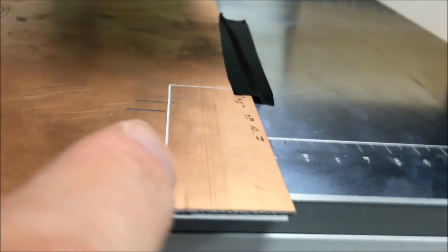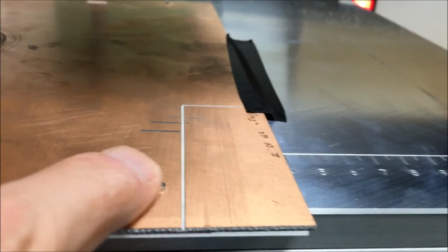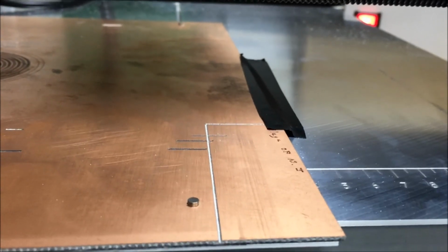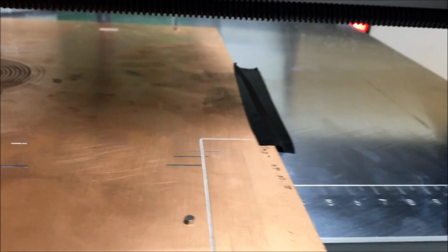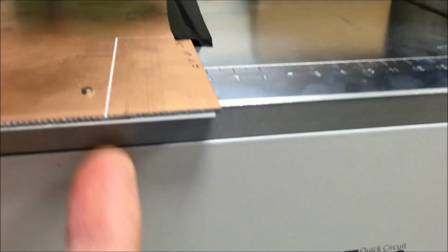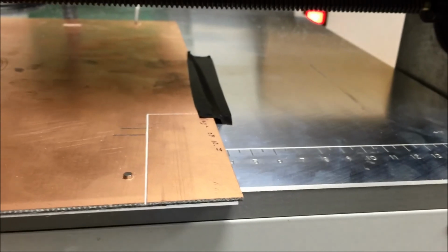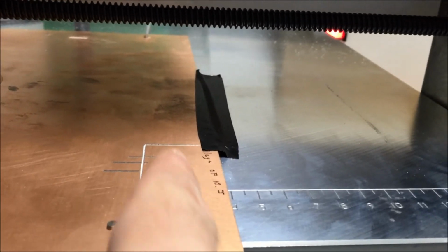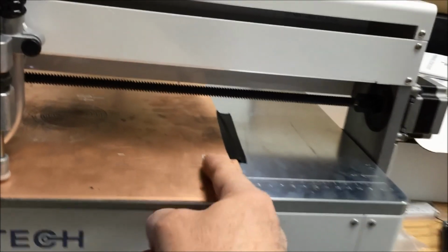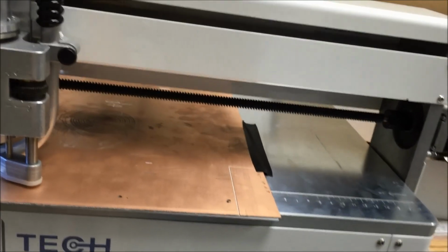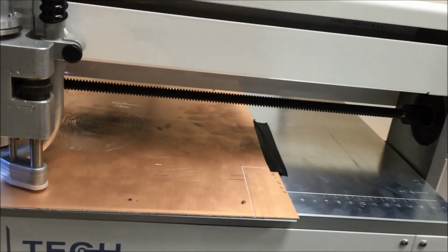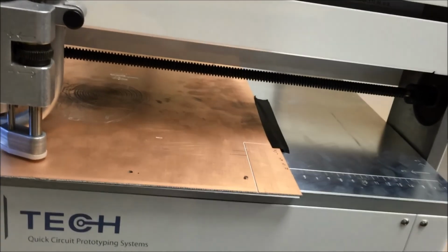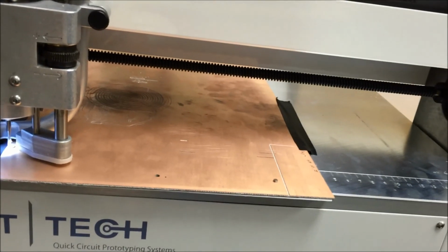So just to point out again, there's a pin that goes through here. There's a hole that has to be drilled through the board. It's 1/8". Okay, and you just press fit the pin through the hole, and it goes into a hole in the actual platter of the machine. And then there's another slot that runs all the way up and down the machine in this axis, a groove, and then the other pin just rides in the slot, and then the 2 pins together keep the board immobile and give you a reference that if you were to flip it, you would be able to register the front and the back sides of the board.